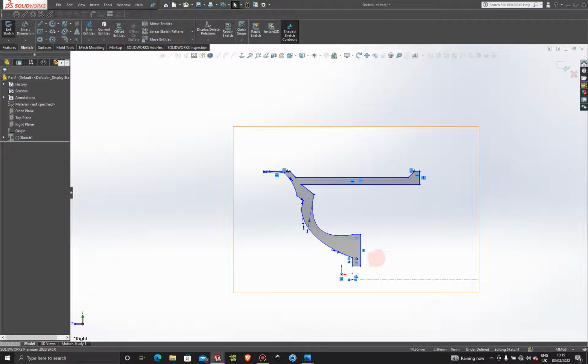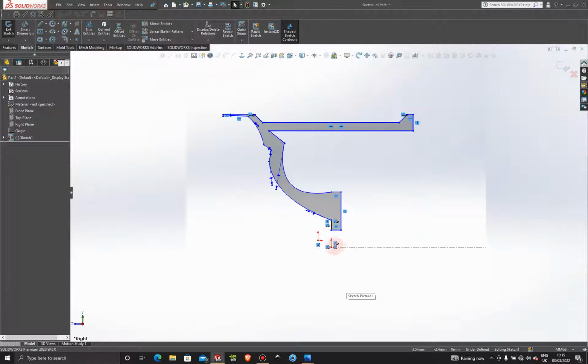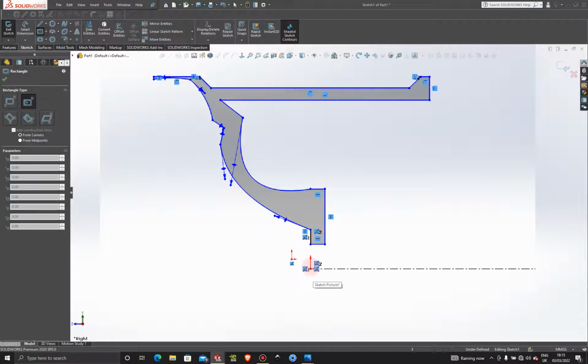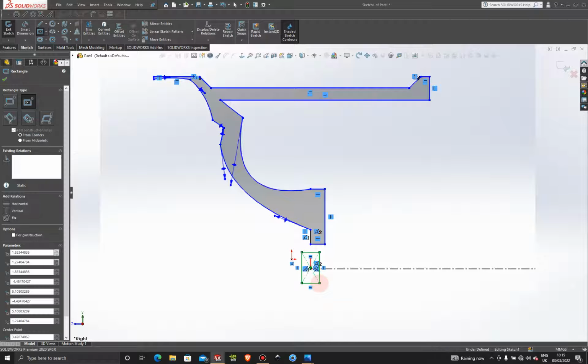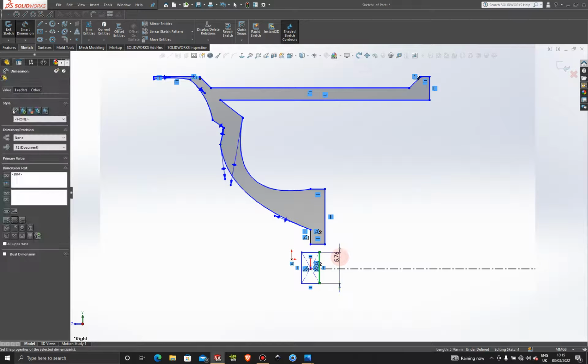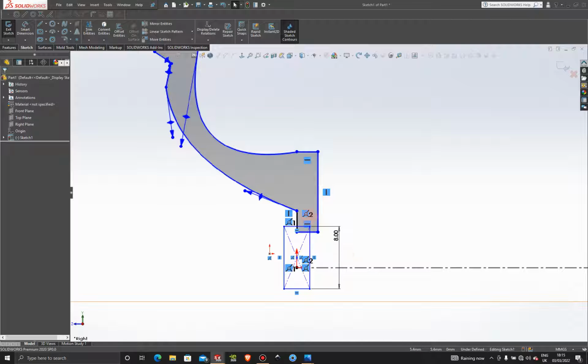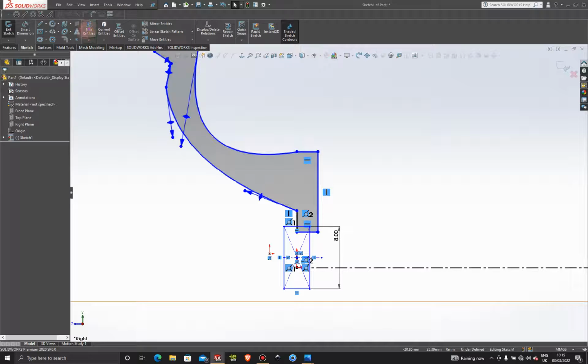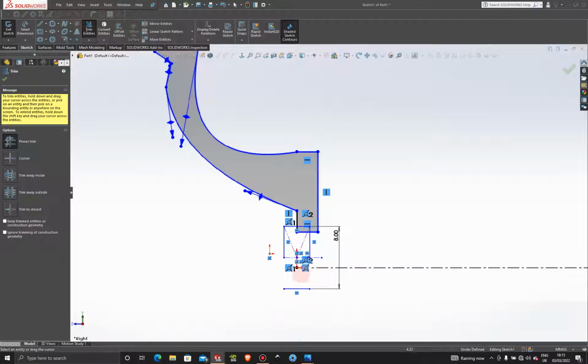All right. And then I just want to make a box here in this general area. I want to make sure that we have our sizes there. Perfect. So let's grab a center rectangle and just drop that center rectangle about here. And let's give that a smart dimension of 8. All right, so we can already see what we have to cut out. So let's grab this center line here and just cut this in half because we don't need the lower section. Cut this down.